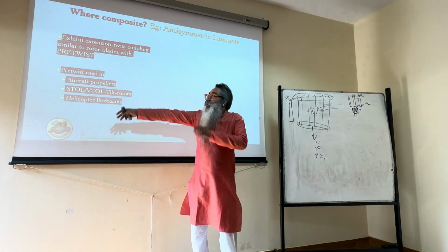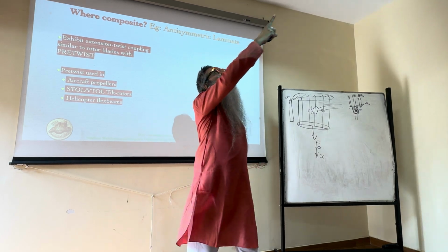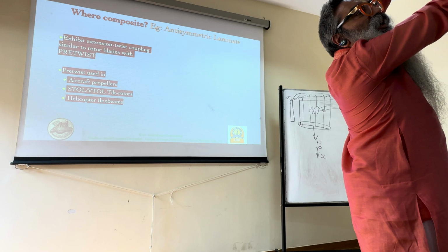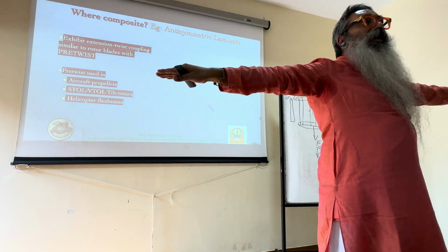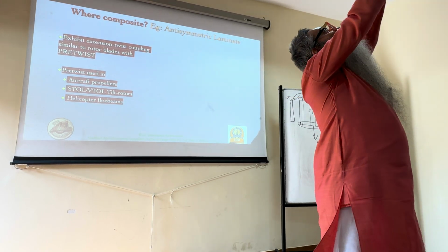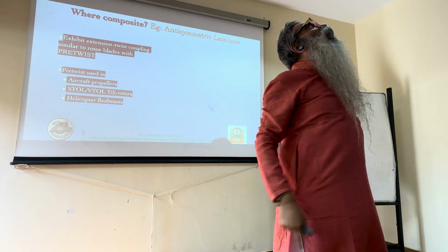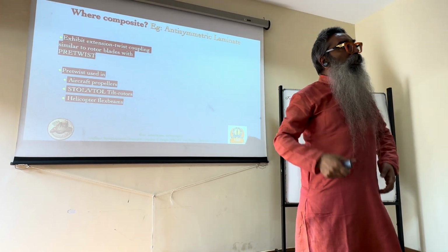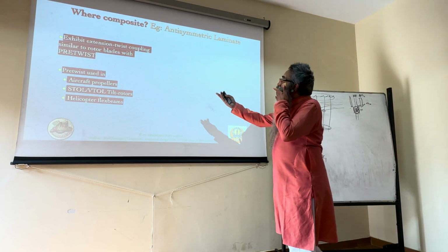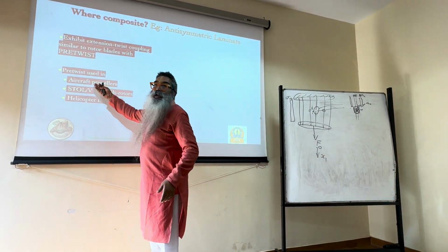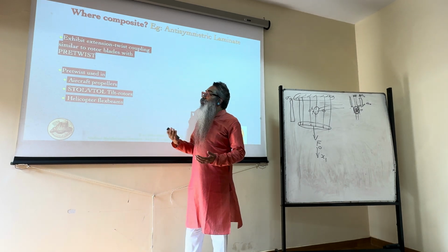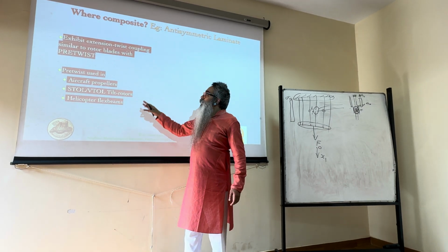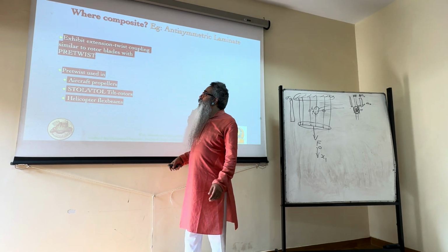So that kind of a thing behaves very similar to having an actual physical geometric pre-twist that you do in the manufacturing. Like many of these fans, if you look at this fan, you see that it's not actually straight, it has a small twist there, okay? Like what in the wings you call wash out or wash in. So something similar to that, you have a twist there. It's much more pronounced in the case of helicopters and wind turbine blades. So used in aircraft propellers also. Fixed wing aircraft also have propellers. If they are turboprop, for example, or piston prop, the older kind of aircraft, you will have propellers there. So those have very large twist, as you would have observed.